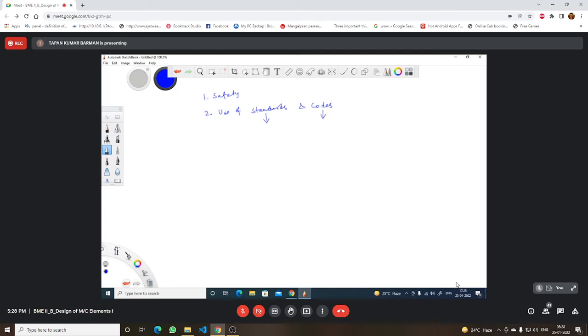Because these products are also readily available in the market. If you try to stick to your dimension of 22.1, you have to customize your products. You have to make tailor-made products for your use only. These are not standard dimensions. If you try to purchase the product from the market, this 22.1 dimension product is not available. So you have to go to the next higher standard value to standardize your product.